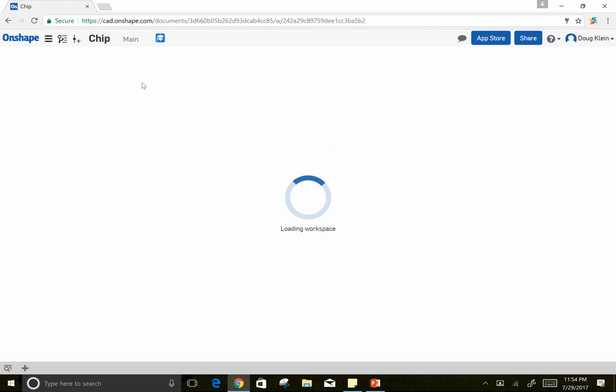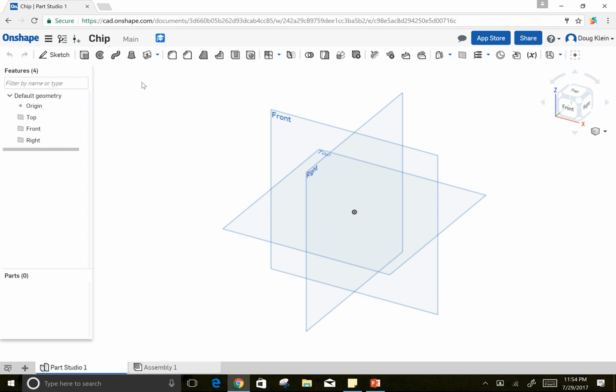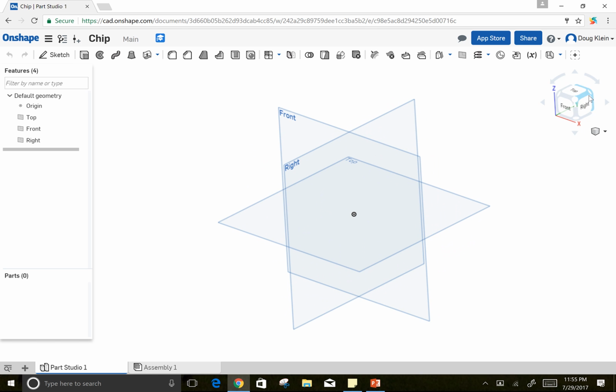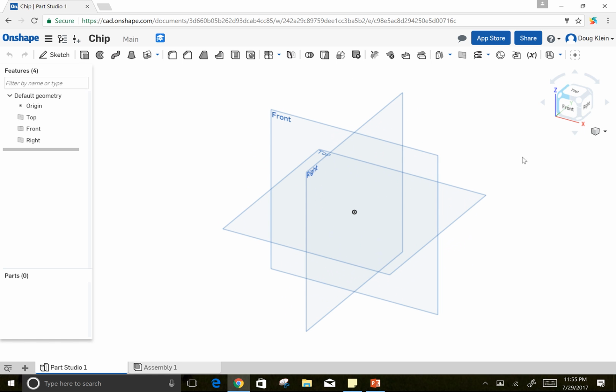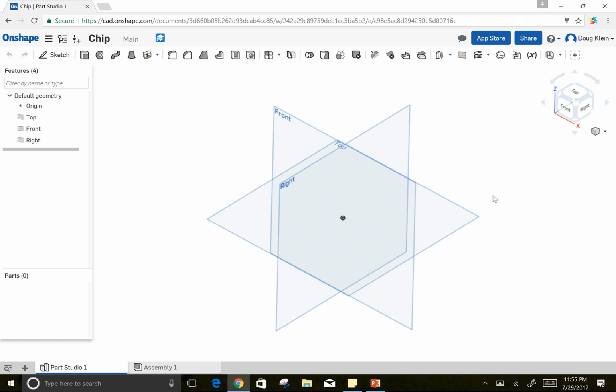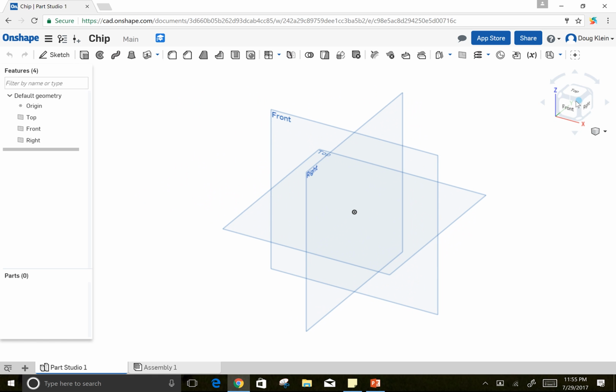With it working similar to Google Docs, you also have the ability to have collaborators on it. I could 3D model over here, and you could 3D model over there, and your buddy could 3D model over here all at the same time, which is a wonderful advantage. If you're a veteran to 3D modeling, this is a very similar interface for you. You have your history of parts, all your tools at the top, your Cartesian coordinate system right here that we're going to be modeling on, and a navigation cube. I can click on this corner and look at it in different directions. I can right click on my mouse and rotate a little bit. I can push down the scroll wheel and move things around, or I can always go back with my navigation cube.